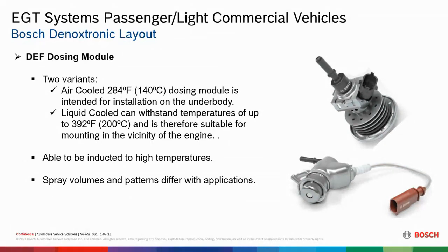And there are some close coupled systems that are newly coming out. There's a Mercedes, several years old now, that Bosch has designed the after treatment system for, that's right on the engine. So the whole after treatment system is right close to the engine, or what they call close coupled. We still do use DEF to dose in there, but we don't use hydrocarbon dosing anymore in those systems. So if you heard that, and this is one of the things I hear, well, I heard they're not dosing anymore. Well, it depends on what they're dosing. So we call two things dosing: hydrocarbons, that's fuel, and we call the DEF fluid dosing as well. So no systems that I know of yet have eliminated DEF fluid. We're still using that in every application that I know of.